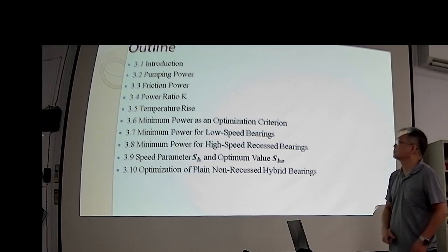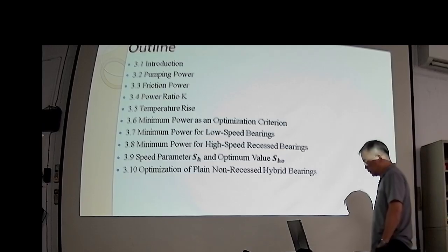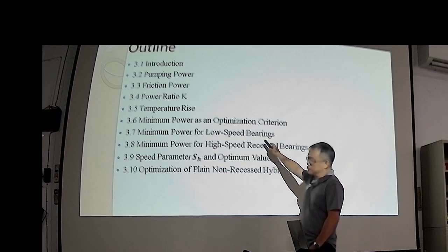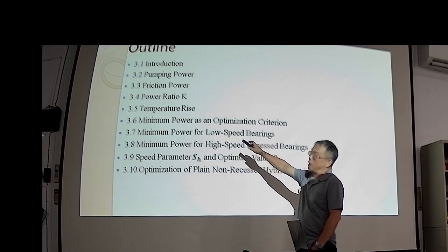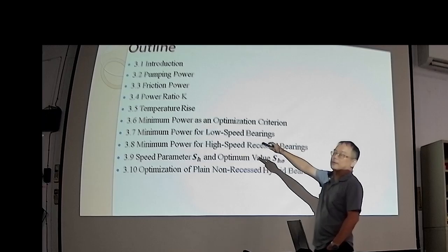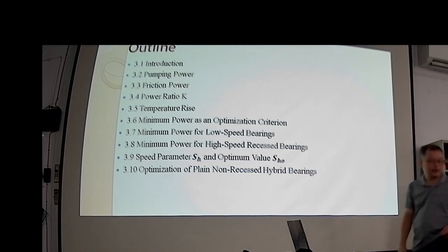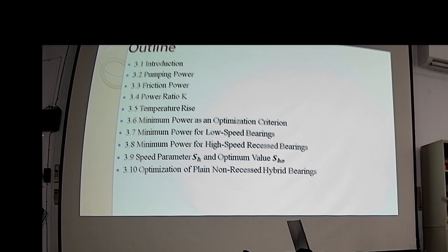We have some design tips. If the design objective is minimum power, which means minimum total power for running the hydrostatic bearing, then the bearing will run with very low friction power and low pumping power.